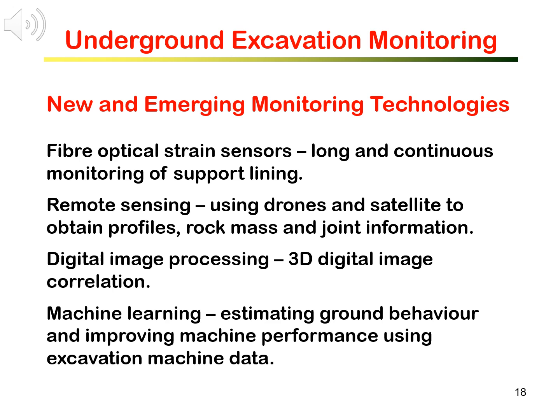Monitoring technology has been progressing and developing. One of the major developments is the use of fiber optic strain sensors, also known as FBG, fiber Bragg grating sensors. With the fiber optic cable, we are able to perform long and continuous monitoring of the concrete lining around the whole circumference or along a long length.